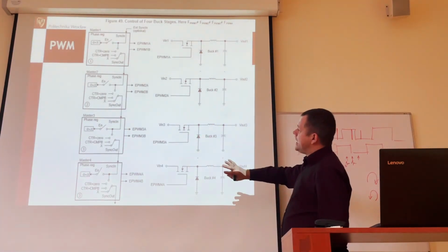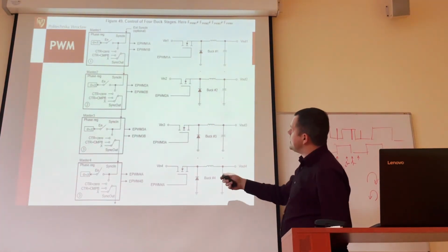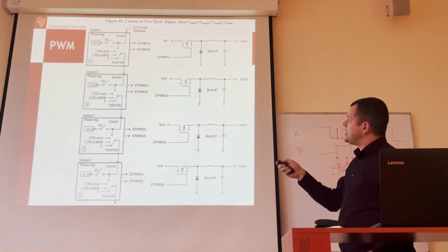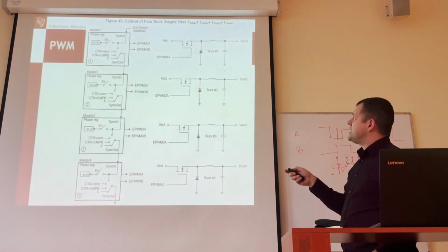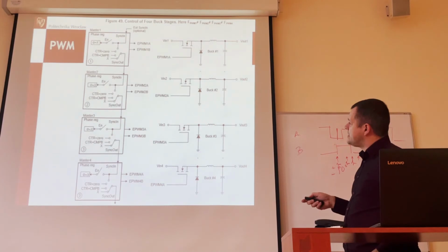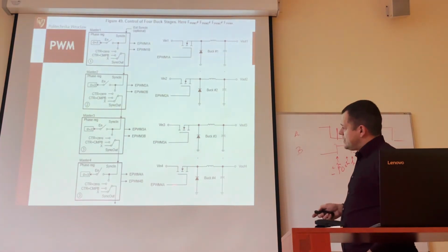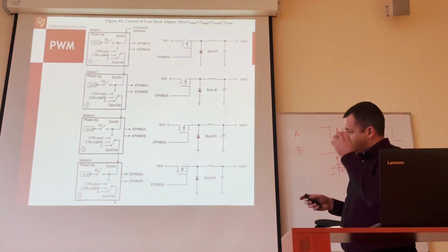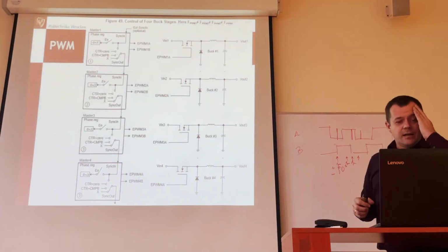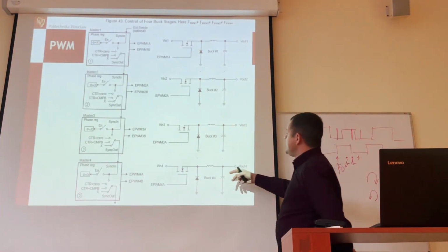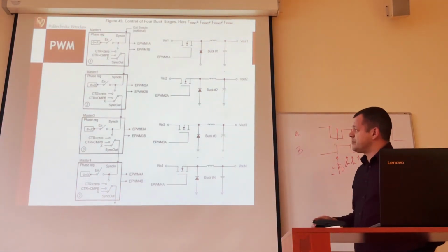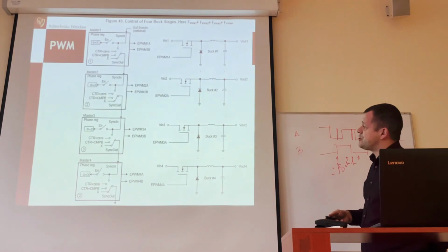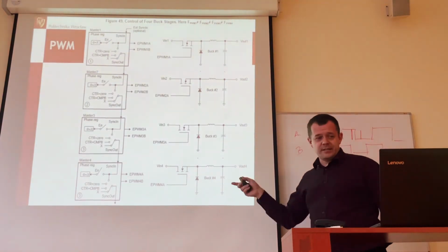Another interesting application in case of microcontrollers is synchronizing the PWM. Here we have a sample situation where we have one PWM driving some DC-DC converter, another PWM, another DC-DC converter, another one, another DC-DC converter. Of course, theoretically, it's possible that each DC-DC converter works independently. That's the simplest possible operation, so no synchronization is switched on.